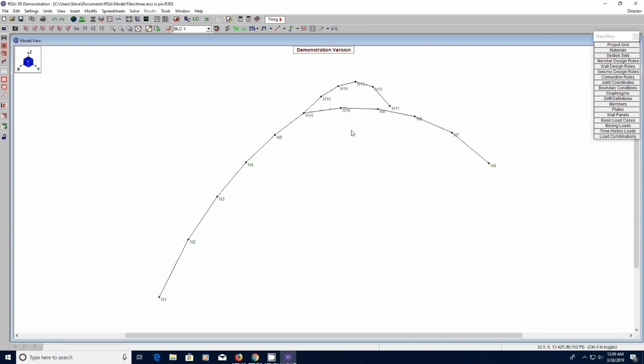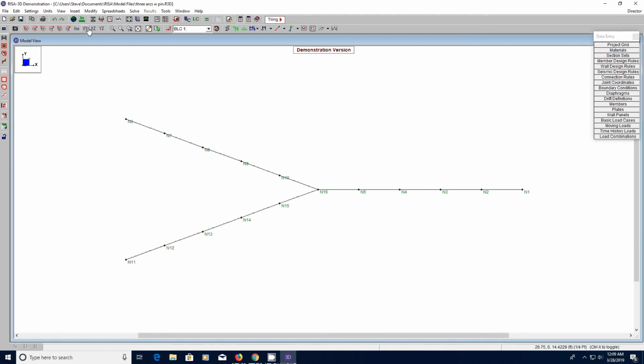This is, let's say, three arcs coming together, arches coming together. I'll actually create a pin here. It's similar to a three-hinged arch, except I'm doing it now with three pieces versus the typical three-hinged arch, which is a flat arch with a hinge there, a hinge here, and a hinge here. So we're doing it by adding this additional segment here, and then this is kind of bent off the axis here. So if I look at it from the top down, the XY, the typical three-hinge arch would be straight all the way across. So I've got two of them on this side versus the one.